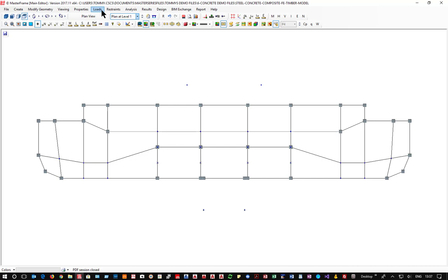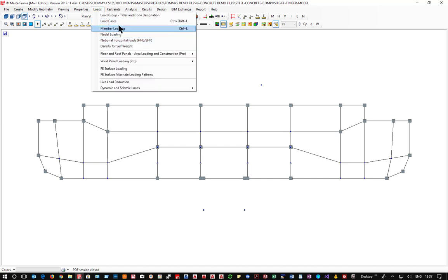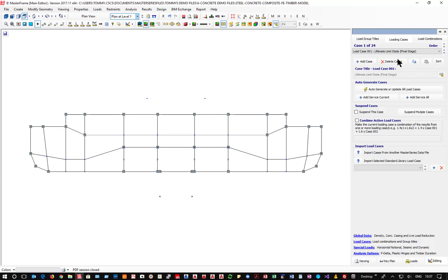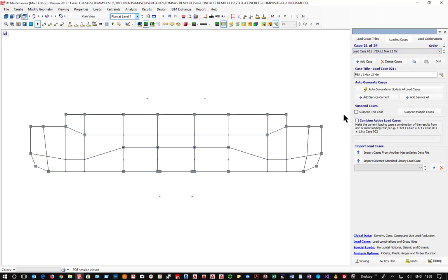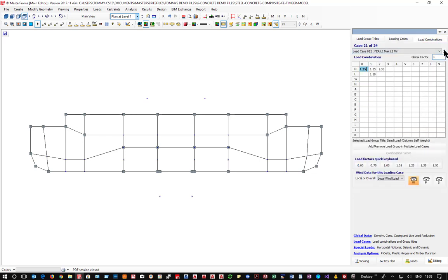Well, those patterns are then used if we look at the loading cases and we come down, not to the composite and the wind loading cases, but to my pure concrete design cases. I have a FEA live 1 max, live 2 min, so max min. If I then look at the again, I have a min and max. Or if I go to my permutations and look at them, I have dead loads and then maximum only on my L1.